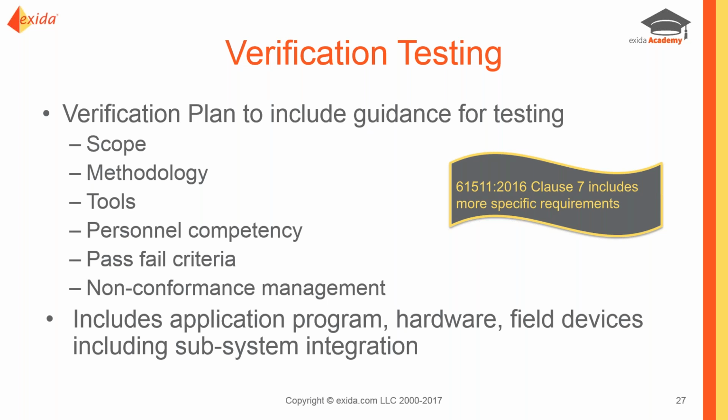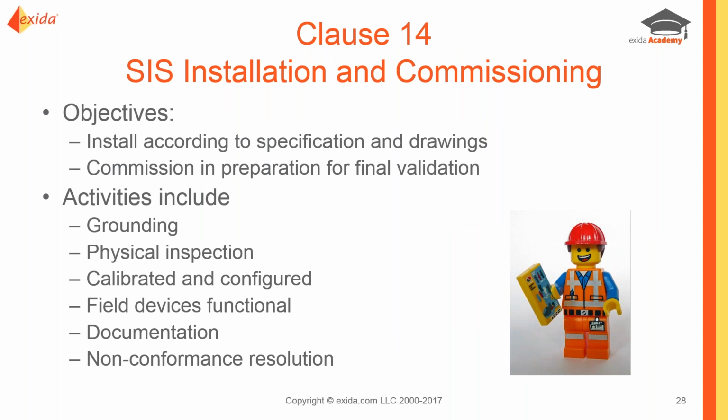The field devices need to be exercised and tested in a number of ways to assure their integrity, and that's not just calibration and continuity testing. There ought to be full proof tests that go with it. So this verification testing is a very important part of the validation activities.